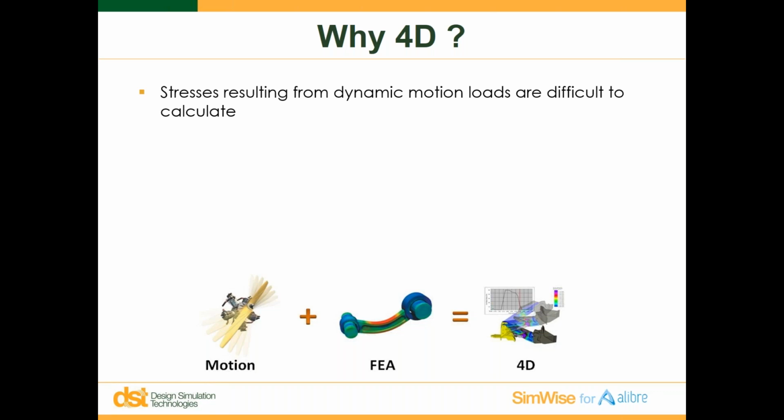Why do we call it 4D? Because when we look at using loads that result from dynamic motion simulation, these loads are difficult to calculate. Typically, a prototype is built and instrumented, and loads are obtained that way. Also, peak loads do not always equal peak stresses.